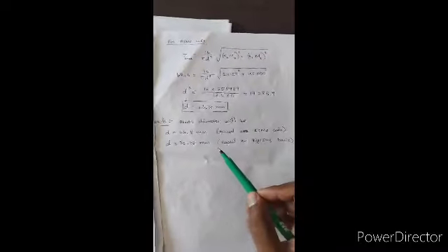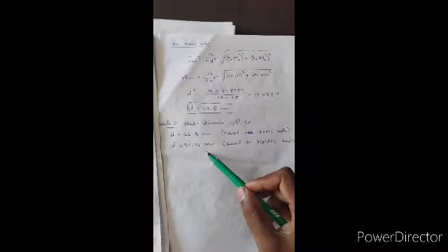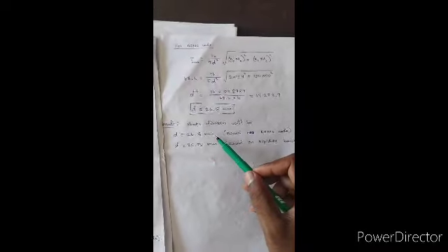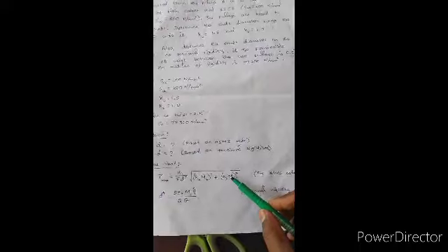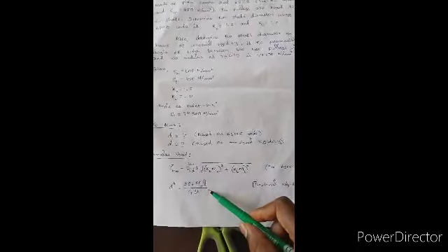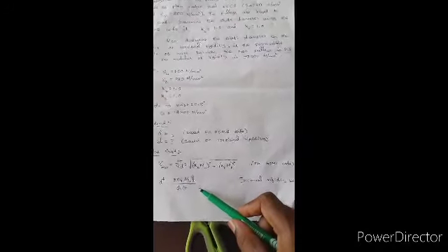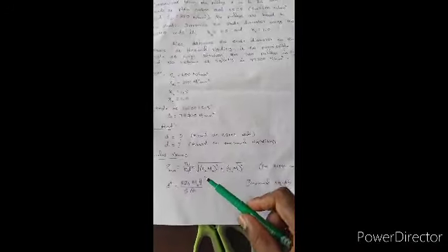So based on the rigidity method, we got 25.78. Based on the ASME code method, we got 26.8 mm. So this is the diameter of the shaft using both methods. This is very simple, only two formulas. This is for the ASME code method, and this formula is for the rigidity method. But the thing is, you have to find the MB value and MT value.